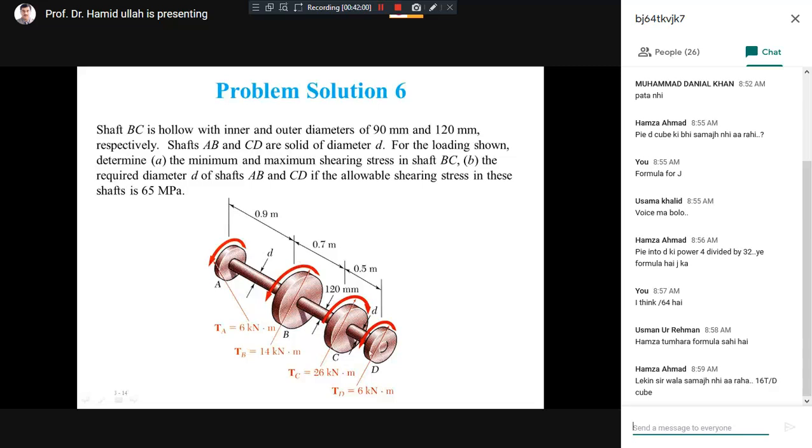And then you can see at C there is a load, at point D there is a load, so you can section the shaft. And again, you can consider the left side or the right side. Then you draw the free body diagram and apply the equilibrium condition, and you can get the required quantity of the resistive torque. So this is how.